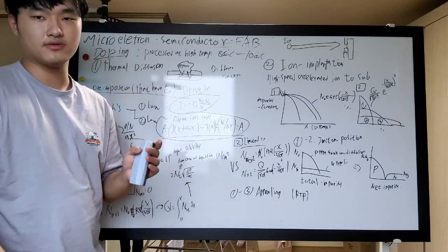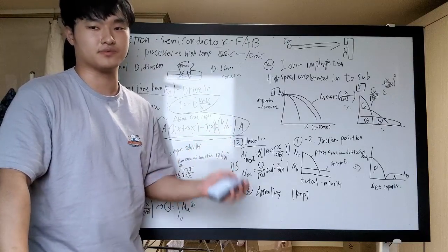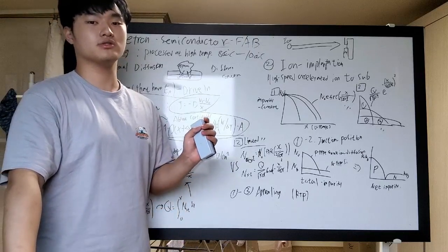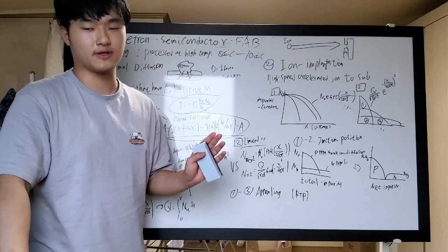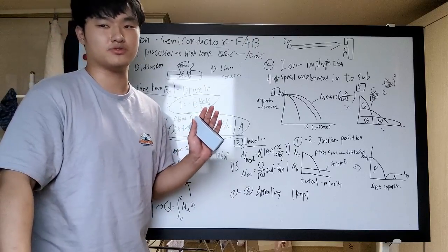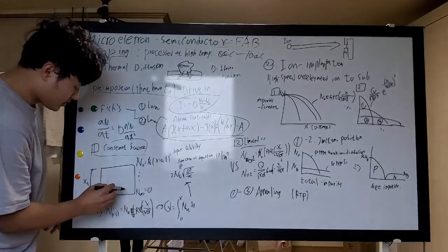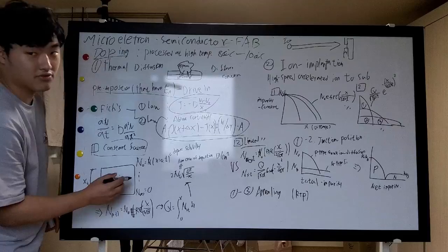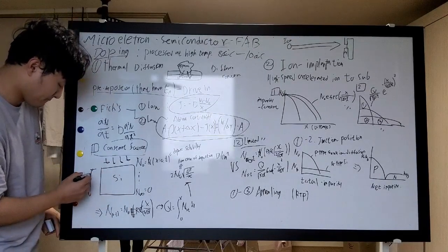Of course, if there is enough activation energy and the conditions allow doping, such as the dopant having enough energy to break the covalent bonding between the silicons and make another link or connection between the silicons and the dopant like borons. So this means, let's say this is a silicon and we started doping on the surface.